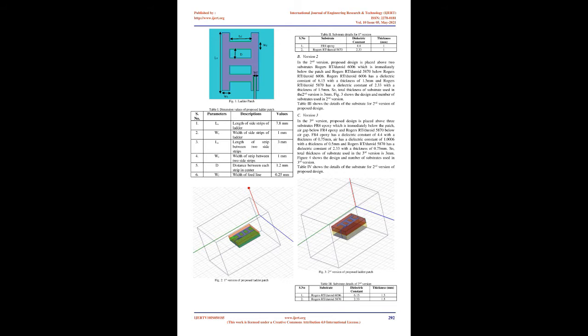The design proposed in this paper is a ladder-shaped patch, which can be used for applications in the frequency range of Ku-band, 12 GHz to 18 GHz, such as radar guns, satellite television, satellite communication, etc. This was designed with an efficient software tool, HFSS, High Frequency Structure Simulator.